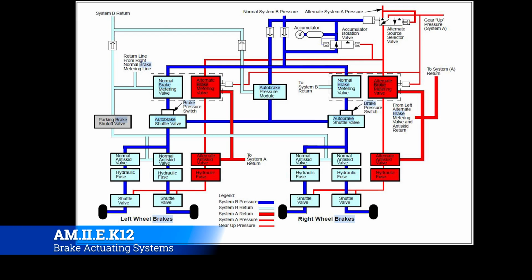And note that there's not any nose gear braking. That's common on pretty much all aircraft. I've never seen a nose gear braking system. Not to say it's not out there in some random model, but I'll tell you for a 737 and all your other heavy commercial stuff, the nose gear is there to support and to steer, not to brake.